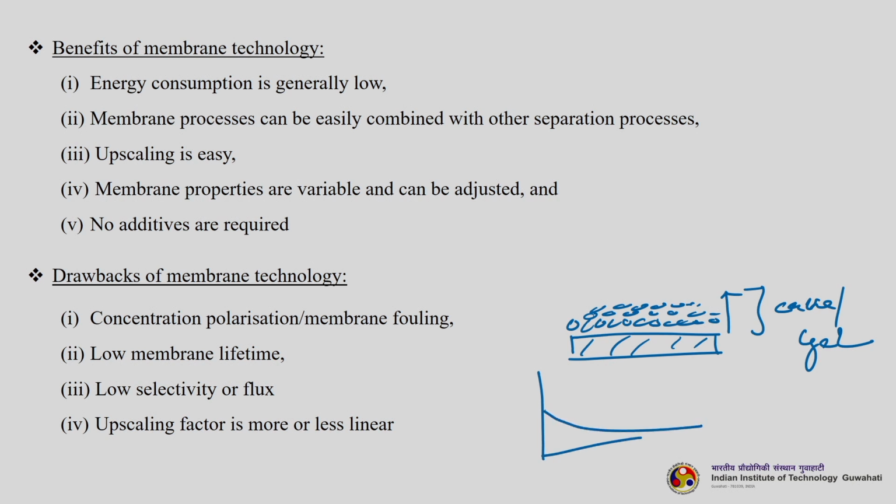That is because it is providing a huge resistance to the flow, either this way or this way, it does not matter, gradient filtration or closed flow. So, flux versus time. And the second thing is that it will also result in fouling. Fouling can be external fouling, it can be internal fouling. Internal fouling means the foulants getting trapped inside the pores of the membranes.